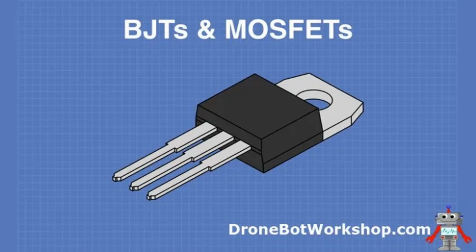5. Source and drain regions. The source and drain regions are heavily doped with impurities to create low-resistance contacts for current flow. The doping level of these regions is significantly higher than that of the channel to ensure efficient current conduction when the MOSFET is turned on.